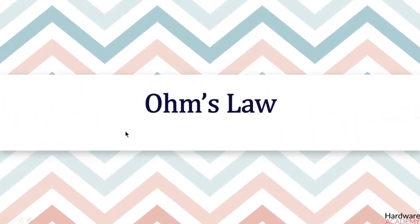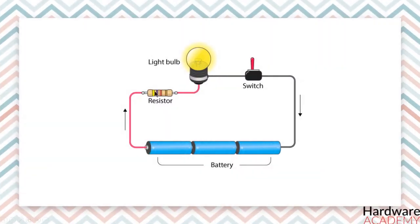Alright, so in the previous course we talked about resistors, and now we know that resistors are used to limit the current in a circuit, right? So let's imagine that we have this circuit and the light bulb requires 1 ampere in order to fully glow. We also have a power supply of 5 volts, and the question is, how do we use a resistor, or a better question might be, what value of the resistor should we use in the circuit in order to set 1 ampere of current to flow in the circuit?